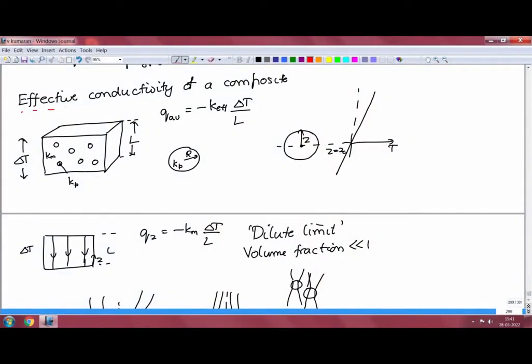In the last few lectures, we had looked at solving the diffusion equation, Laplace equation if there are no sources or sinks, or what is called a Poisson equation if there is a source within the domain. We first solved it in a Cartesian coordinate system for the heat conduction in a rectangular block as well as the flow in a rectangular channel. And then we were trying to solve it for a spherical coordinate system for the particular problem of the effective thermal conductivity of the composite.